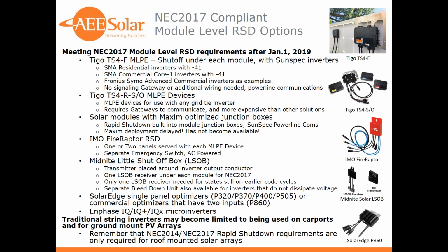compliant inverters. The SunSpec compliant inverters basically provide a heartbeat and a signal to these shutdown devices, and as long as that signal is present over the existing wiring, over the power line wiring, the DC plus and minus wiring, that device stays in the open position and allows the module to be connected to the system. If it loses that heartbeat, if it loses that signal, then it performs a shutdown. And then the inverter would handle the bleed down there.